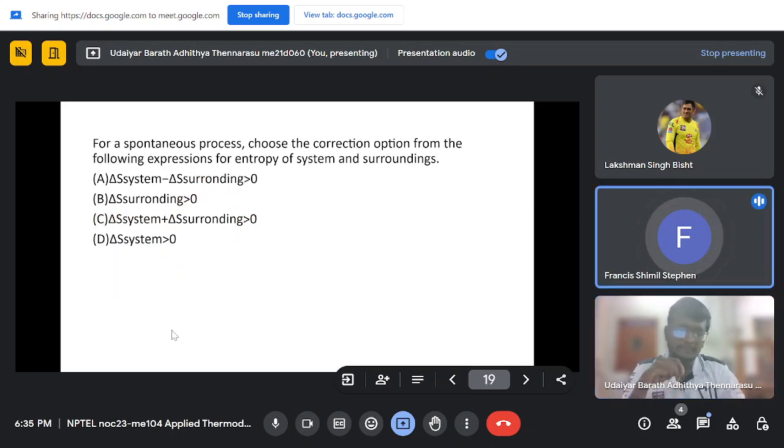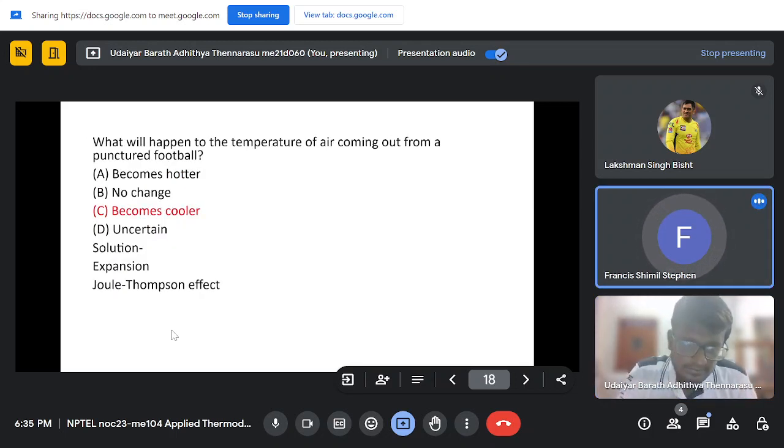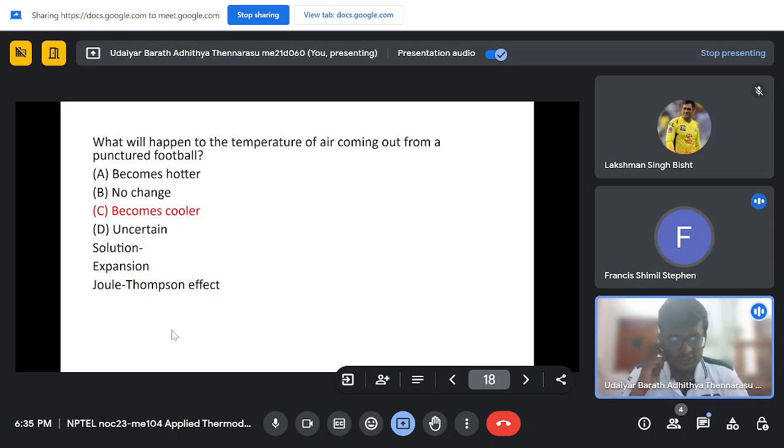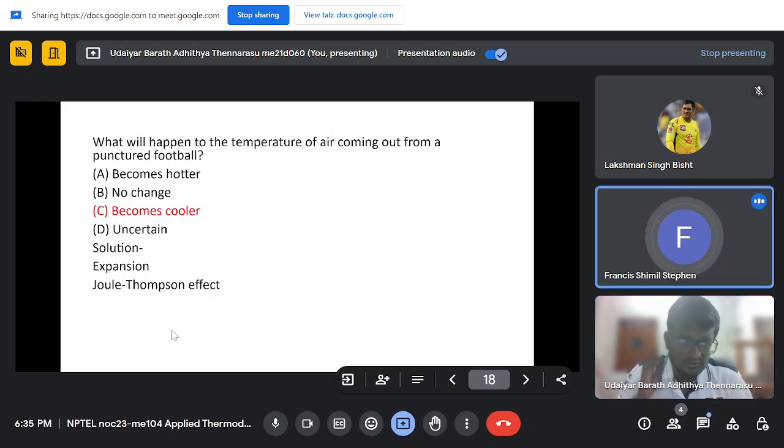So this fuel compress effect is called throttling, isn't it? Yeah, it's called throttling. So I have a doubt: for throttling it will be an isenthalpic process, isn't it? Yes. But for a nozzle also the area is reducing, but we get another formula for that, in the form of V1 and V2, when we apply the steady flow equation. Why are we getting two equations for that?